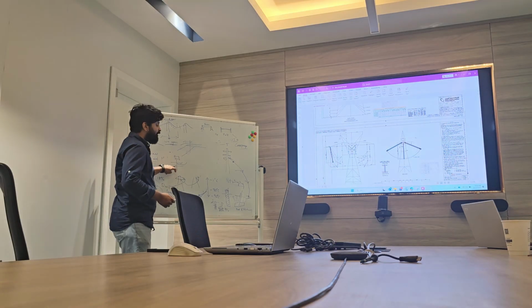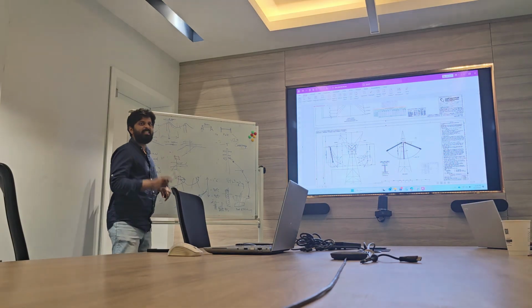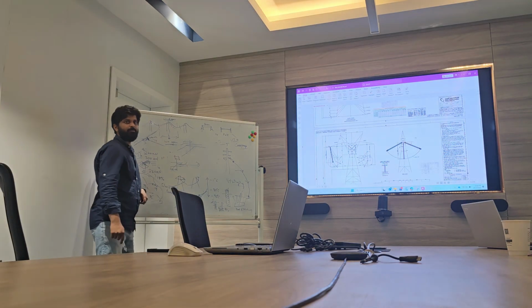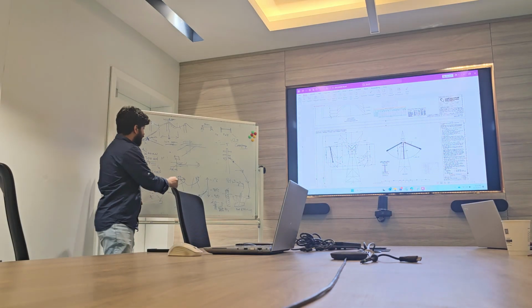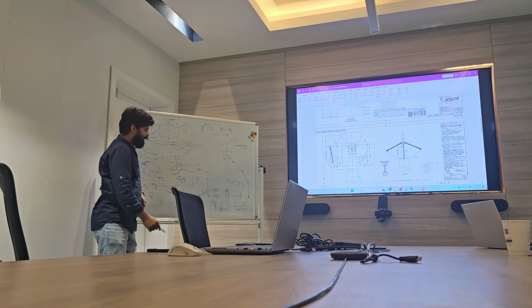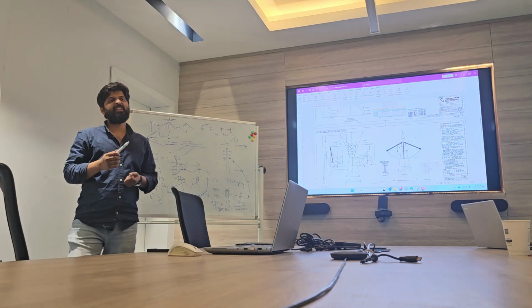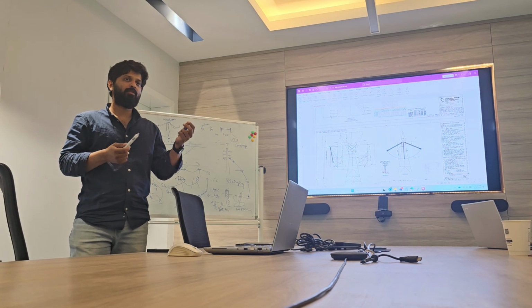In this design for a suspension tower, you don't apply any tension on the tower, except when this wire breaks, this wire will pull this tower to this side. That's called a broken wire. Or, before you put any conductor, you have a tension tower here and a machine here, and you will pull this conductor. At the time of pulling, this has some force. That's called stringing. So a suspension tower has only two types of longitudinal loads.